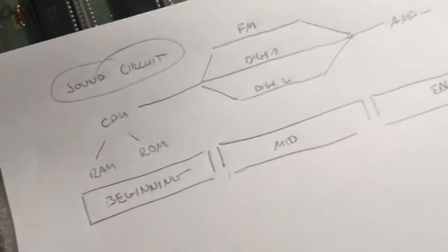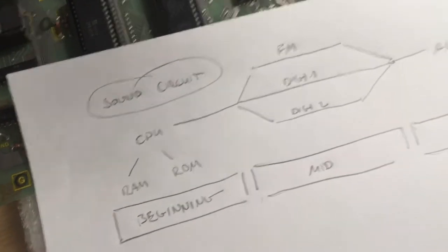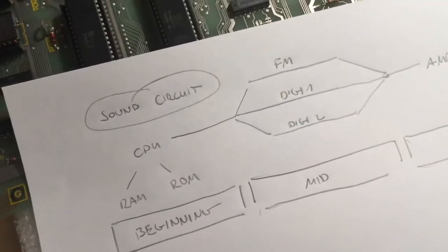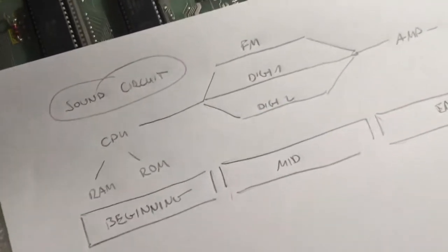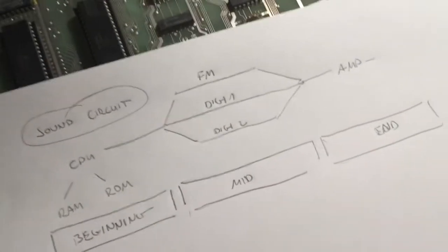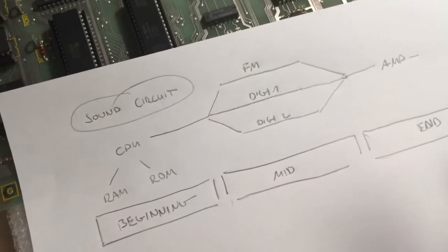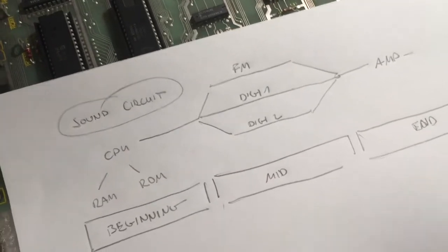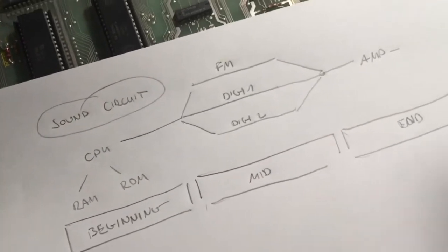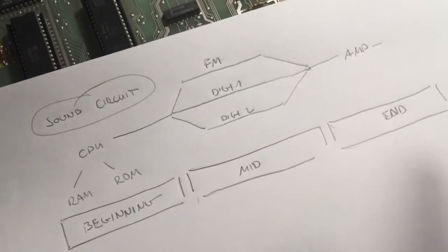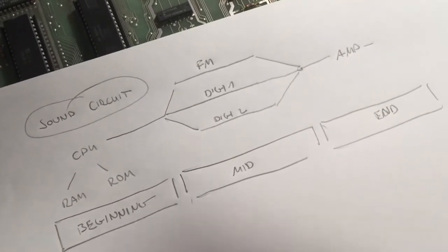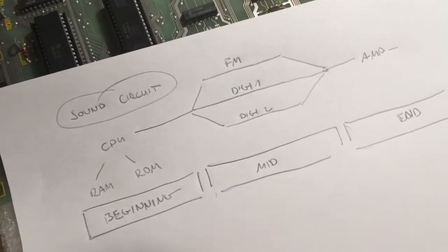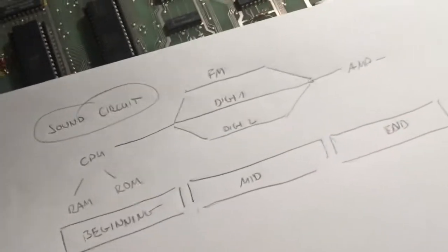And if you have a failure of the sound CPU because maybe there's no frequency coming from the crystal, for instance, that will lead to a complete shutdown of the whole sound circuit, and you will also hear no sound for a different reason, of course, but the final symptom is the same. So also a failing of the circuit at the very beginning can cause a complete loss of function.